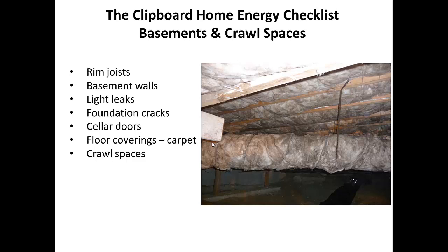And in crawl spaces, you want to make sure that you've got insulation in those areas, because down there is an unconditioned area. And one caution is that if you've got plumbing pipes running through here that have never frozen over time, and let's say this is not insulated, but you've never had any problem with freezing pipes or anything like that, now you're going to insulate.